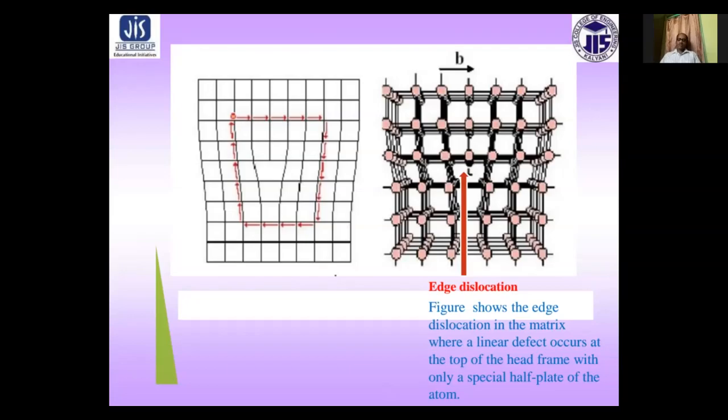The Burgers vector of a dislocation line can be found by using the Burgers loop or circuit method. A Burgers circuit or loop is formed by taking equal integral lattice translations in each pair of parallel sides in the region of interest.